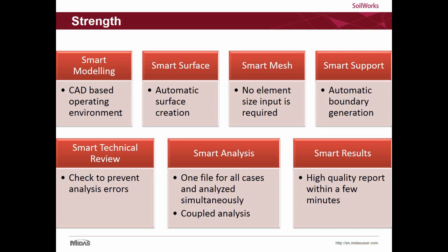Now that the drawing of our model is ready, all the surfaces to assign the properties of soil can be generated with one single click. And that is what Smart Surface will do. It will automatically create surfaces. Smart meshing, wherein without much of a manual effort of sizing the mesh, MIDAS SoilWorks automatically works it out according to the model requirement. No worries with nodal connectivity, thus eliminating errors as such.